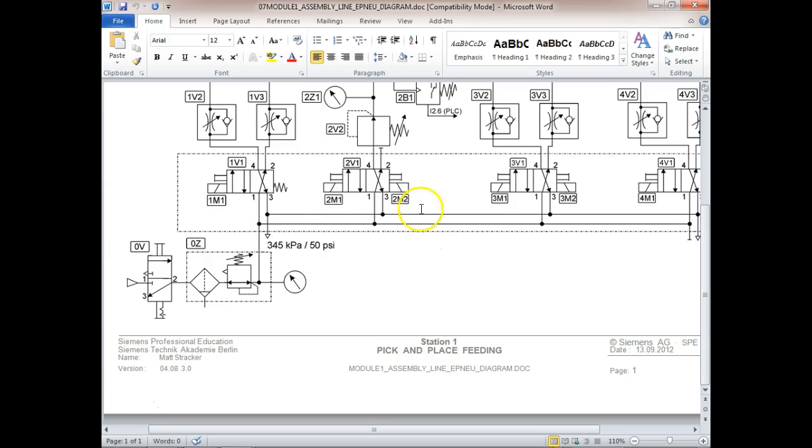Now this is double solenoid operated with a what? Manual override. Yeah. See that? So all these, notice the valve in here is the same. And what's really neat is that the valve doesn't care what shifts the spool. So a lot of times the valve assembly itself will be the same, and what you clamp onto the side depends on how the valve's operated. So these companies don't make a manually operated valve. They make a valve, and then we attach to the sides how we want to operate the thing, which is pretty neat.